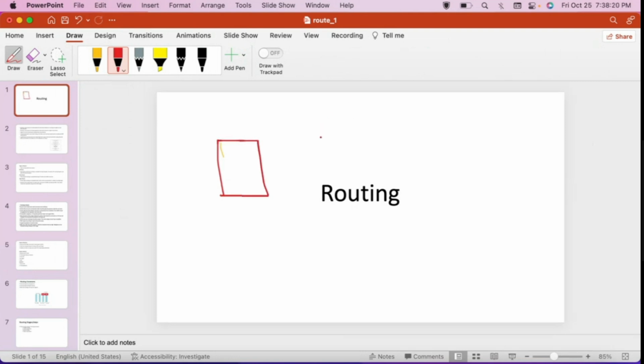So till CTS, you don't see signal routes. We have three types of routings, I will let you know first. Now this is one cell, which may be either a flop, any logical cell, or a macro.